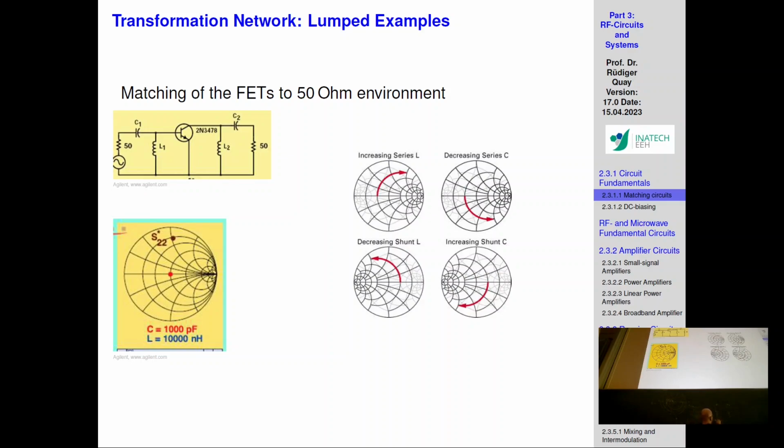And here, once your RF small signal has entered through here, because it's a short circuit for the small signal, you don't want your small signal to go up here. So that's why you have a shunt inductor, and this inductor for high frequency signals will be as if it's an open. You can realize this with a microstrip line.